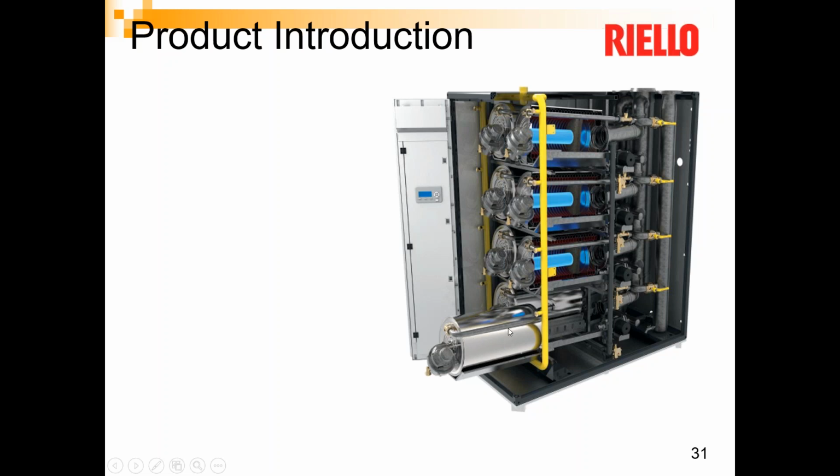And if you ever have a failure on one of the modules, you can simply pull that module out and replace it. It also is great for spare parts. On every Riello Array boiler of any size, the gas control valve is the same, the blower motor is the same, the igniter is the same, and the burner is the same. So it doesn't matter if you have a campus-wide solution and you want to have multiple boilers of different sizes throughout your campus, all of your spare parts for each boiler are going to be the same. All the heat exchangers are the same, the burners, the igniters, the gas control valves, the air dampers, the fans. It really provides for having a nice amount of spare parts. It really reduces the overall amount of spare parts that's needed to keep your facility running uptime.